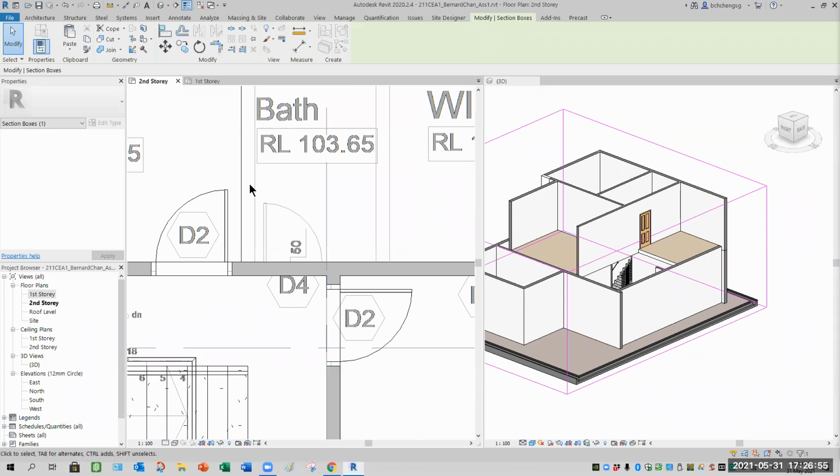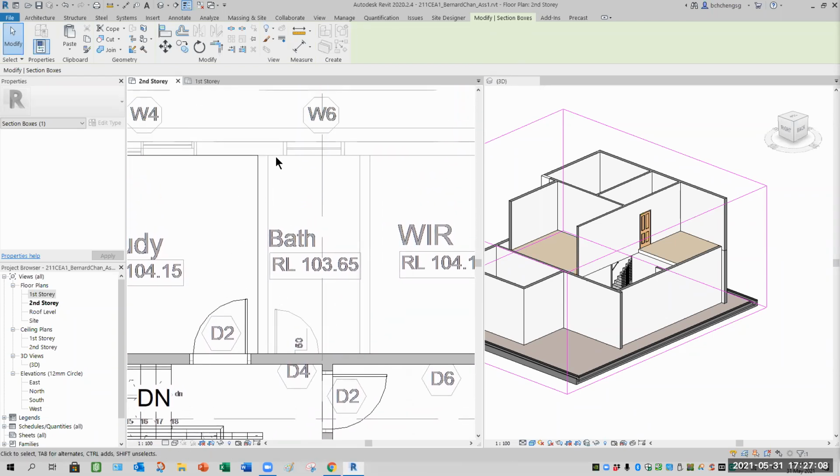So I'm going to create a wall for bathroom, which is the tiles, and one of face is different. So you need to determine which face you are referring. So ideally, all right, for this wall here also, but here's a bit challenging. Because sometimes these are wall in Archicad, we do it separately for detail. That means in another word, we give them as like a normal wall as for just modeling purpose.